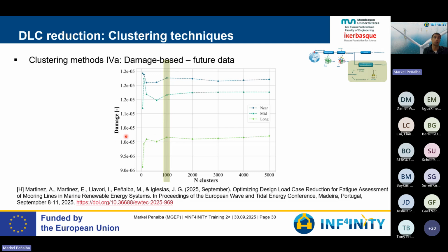But the fatigue damage is purely focused on the operational region, the region where the average is the most representative, and therefore, if the average reduces, the damage itself due to fatigue is expected to reduce under the impact of climate change.